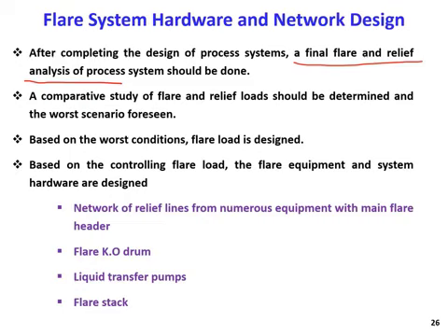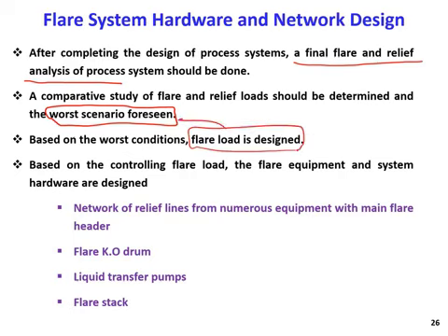The worst case scenario has to be considered. We have to run simulations or comparative studies to consider the worst case scenario and see what will happen to our system. So the load of the flare is calculated based on the worst case scenario. Worst case scenario means we have all types of failures, we have overpressure in all equipment, and this is how we calculate and design the capacity of our flaring system.